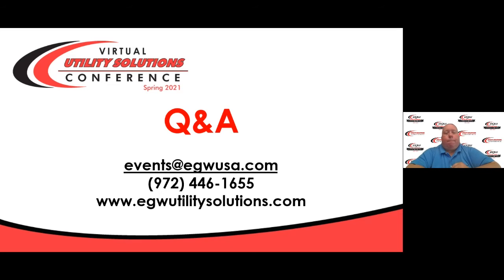Thank you, Daryl. We have another question. This one is asking, how many feet can a 600-foot tracer reel typically travel in one direction? That's a great question. So the maximum is 600 feet, but it's pretty rare that you're going to reach a full 600 feet. I've heard testimony of customers reaching 450 feet. I've seen times when you only get 150 feet. There's various things that can cause you not to be able to push the rod as far as you hoped. Friction is a big problem, and it just naturally gets harder the farther you go.